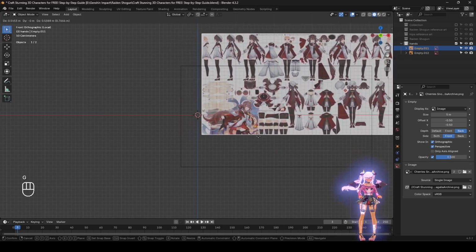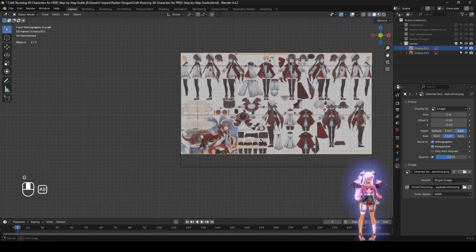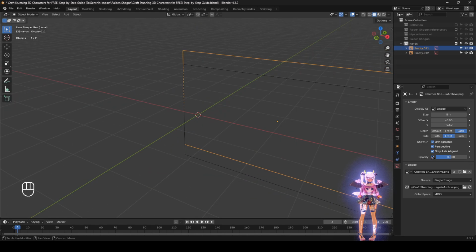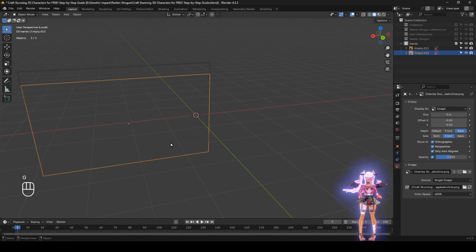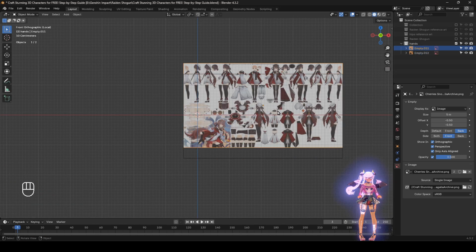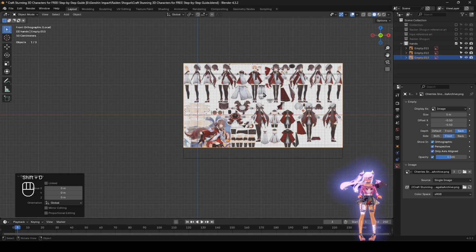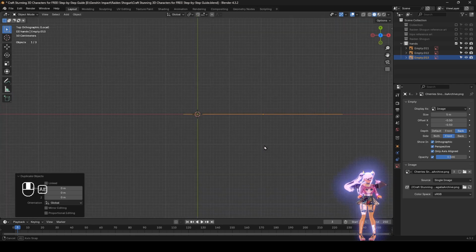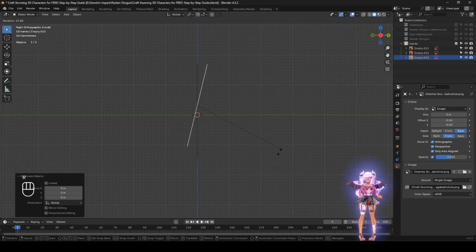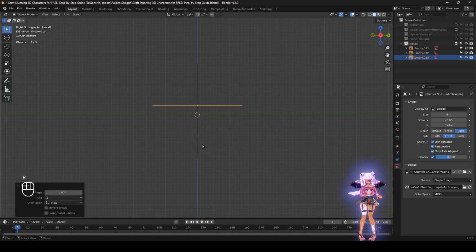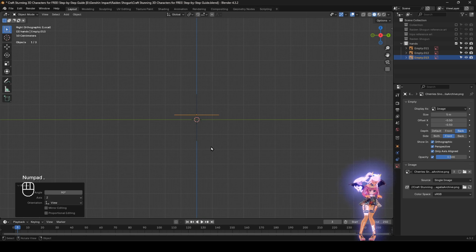Now it's time. Click on the main one again. We only want to see from the axis, so make sure you click both of them so we don't see it. It's up to you if you want to see it or not. So make sure you click on this one, only on axis. Click right here, Shift D, right click, go from above view. Well, first go to this view. Remember, middle mouse button, Alt, depending on views. Do R, hold down Control. About right there, you do 7 on numpad and dot to zoom in on it if you want to.